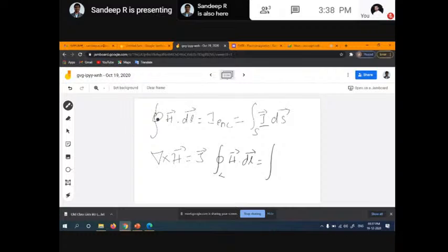That's it, nothing else. Here again, when we are trying to apply Ampere's circuital law, we make sure that there is some kind of symmetry in the current distribution. Whenever there is symmetry, our calculations become easy. We consider a virtual Amperian path wherein the magnetic field intensity is constant, and either normal or parallel to it. We consider H to be parallel in this case so that our integral is simple. So once we have symmetry in the current distribution, we go straight to Ampere's circuital law.